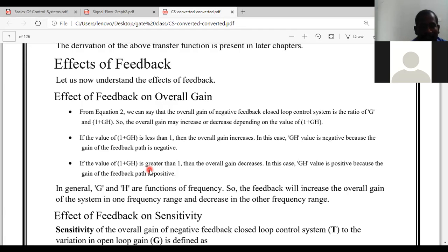Whereas in positive feedback, gain becomes infinite and bandwidth becomes zero, ideally. That is narrow bandwidth and infinite gain. Whereas in negative feedback, gain will be less, whereas the bandwidth will be more, wider bandwidth.